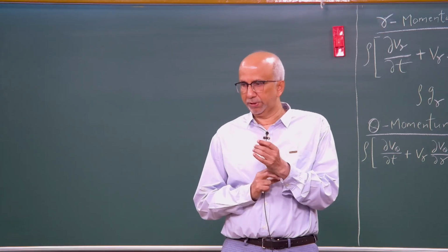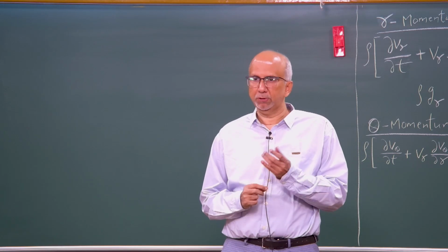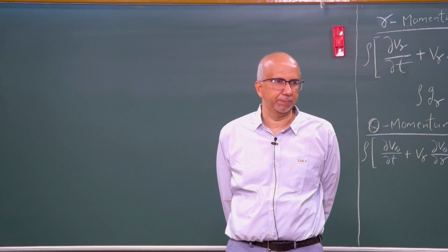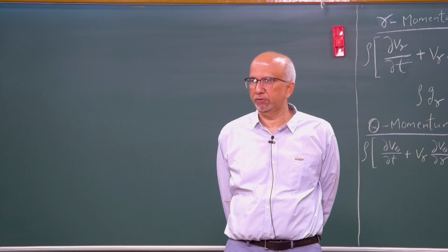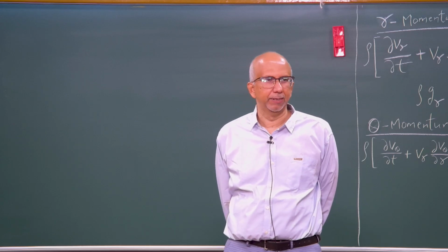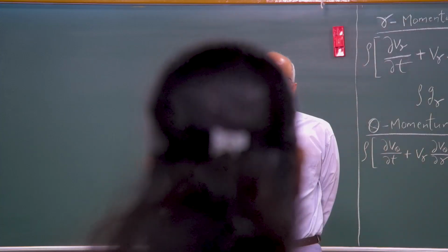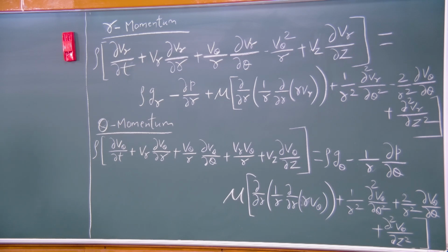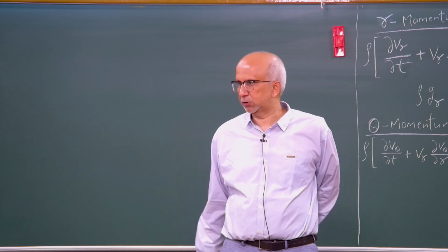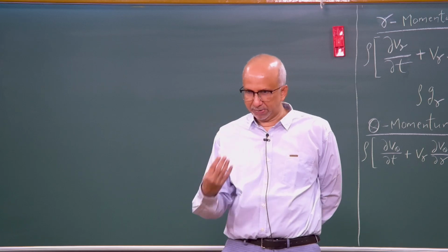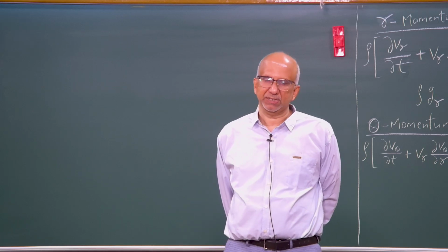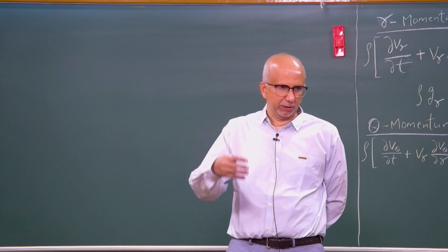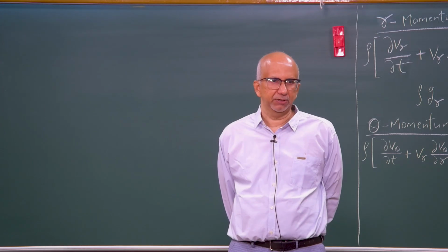So, we are looking at how we can possibly measure viscosity using whatever we have learned so far. And the idea is, if the flow is one dimensional, I mean for the Couette flow problem, I told you that you measure the velocity and the force at one plate which you are moving at a constant velocity. Basically, because the velocity is constant, the force you are applying is balanced by the viscous stresses, and the viscous stresses depend upon the viscosity, and that is the concept you use to measure the viscosity.